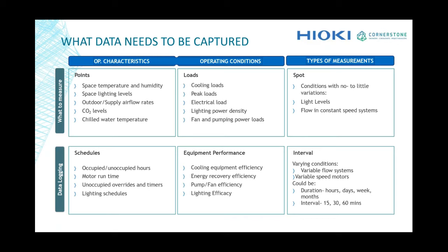So if you're looking at a chiller, we would look at getting measurements like flow, temperature readings, supply and return temperatures. We would look at pressure readings, and finally we look at getting the performance of the chiller either through identifying the COP of the chiller or by having the kilowatt per ton rating of the chiller. So if the data is not available, we would make some assumptions, but again, it's all based on different data that we can get, and we would basically calculate the performance and efficiency of the different systems.